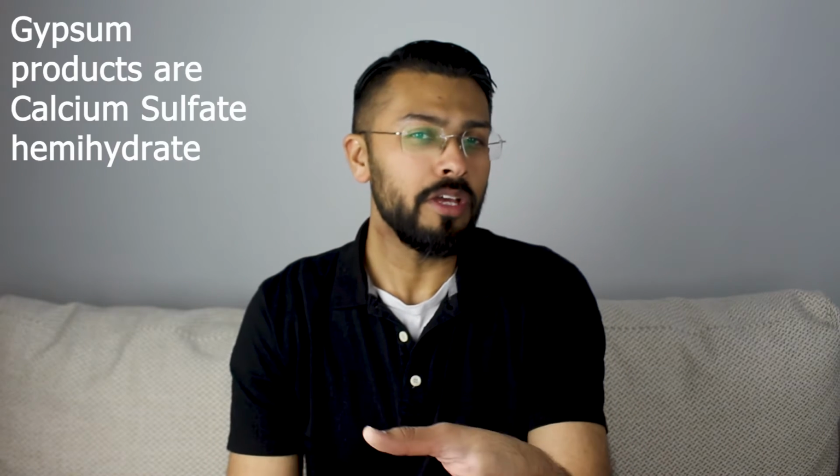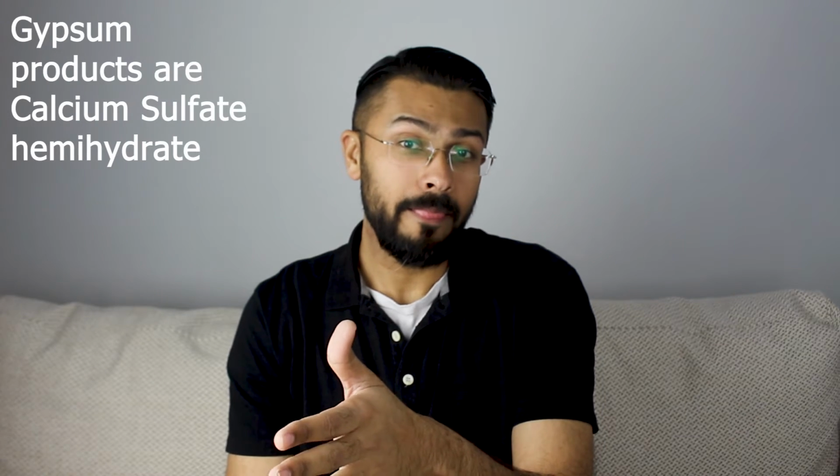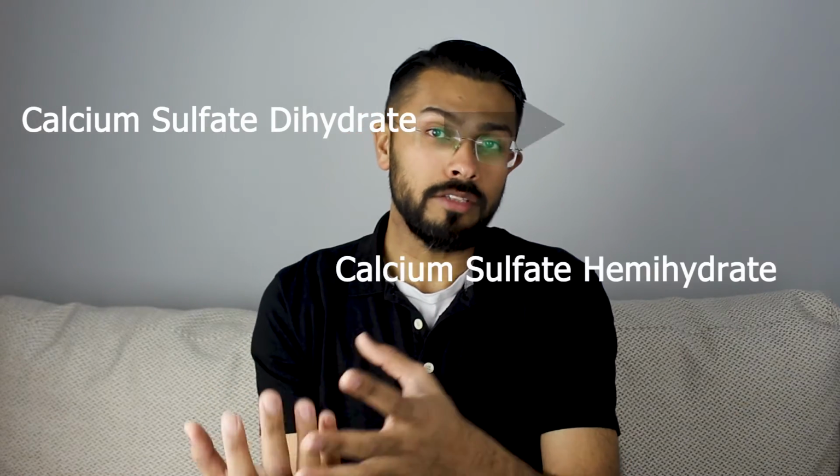So the forms of gypsum products that we use are actually calcium sulfate hemihydrate. They are produced as a result of heating gypsum and driving off part of the water of crystallization. This process is called calcination. So what happens is, due to the heat treatment, gypsum loses its water content and turns from calcium sulfate dihydrate into calcium sulfate hemihydrate, releasing water molecules as a reaction to the heat.